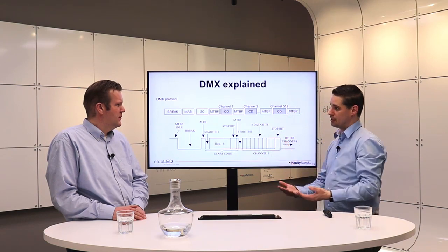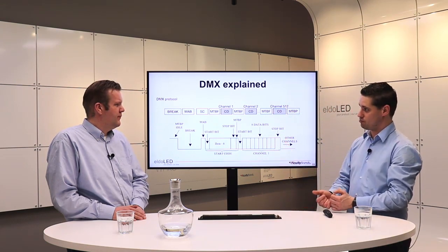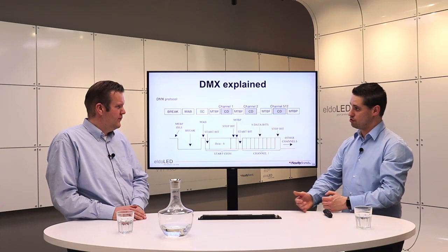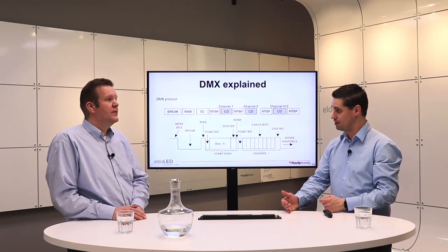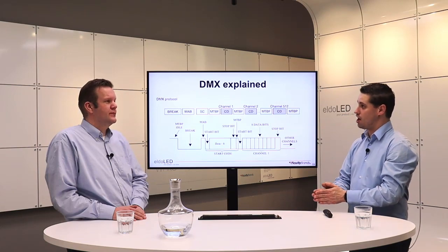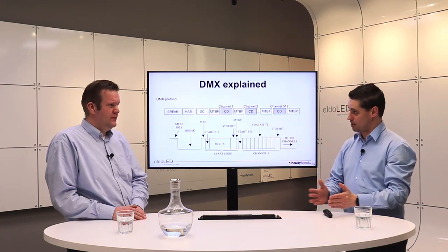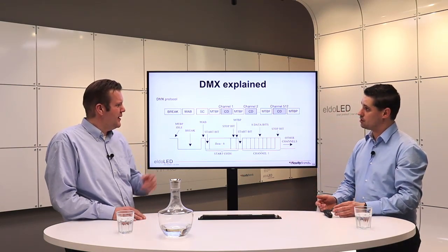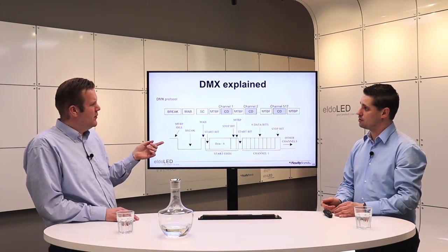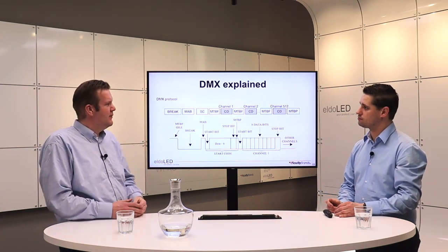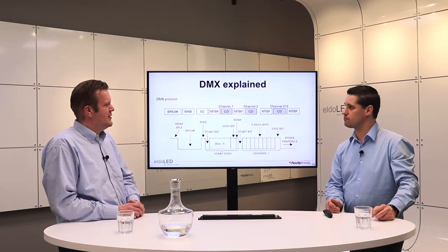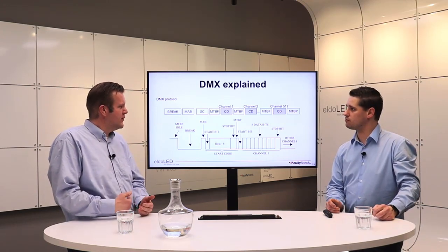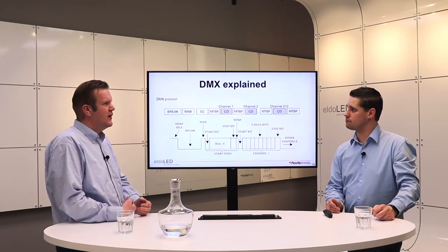So from a dimming level perspective, instead of from 0 to 255, you go from 0 to 65,535. That allows you to have a much higher resolution in step size. Okay. I think that I've seen, in the time I was a lighting engineer, when we used moving heads and scanner heads, you can also select 16-bit, because those moving heads had to turn 720 degrees.